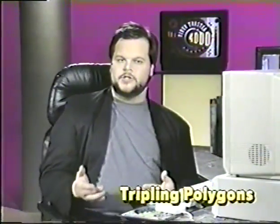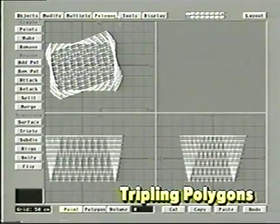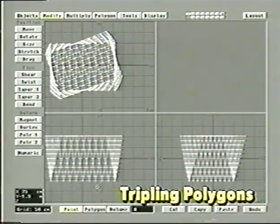And the way around that is by tripling the polygons. So one thing you might want to do if you start really torquing the polygons, really twisting or bending them, changing their shape quite a bit, is use the triple function. Keyboard equivalent is Shift-T. And the triple function can be found under polygon triple. And what it does is it just turns the polygons that exist here into triangles. And I'm not going to do that for right now because I'm not done playing with this shape. But often, I'm just mentioning it right now, if you do something like this and try to render it, you might get some polygons that just won't render properly. So you'd want to use triple there.